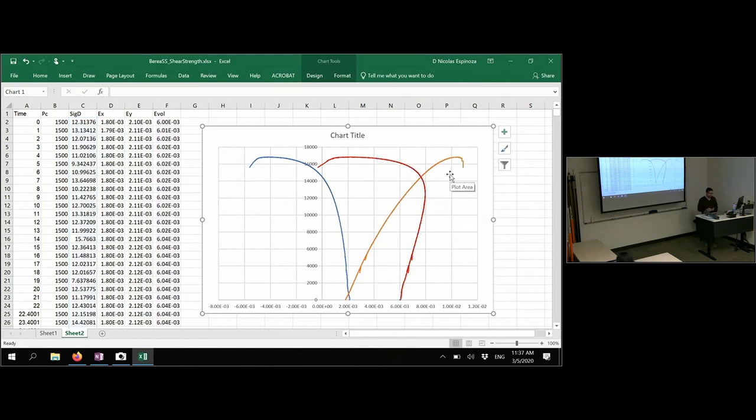When we compress a rock elastically, we add the confining pressure, then we add the compression in the other direction, and you always expect the rock to get smaller. And that makes sense, right? That's why this volumetric strain gets more and more positive, which means more compression or more contraction. However, notice that at around 80% of the maximum stress, the volumetric strain, instead of getting more positive, which means smaller, goes in the other direction.